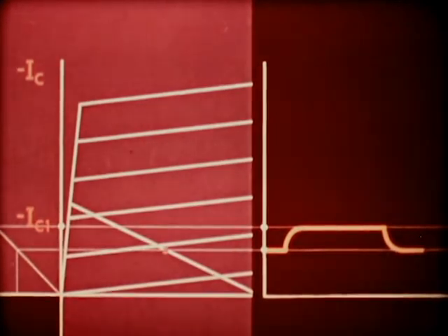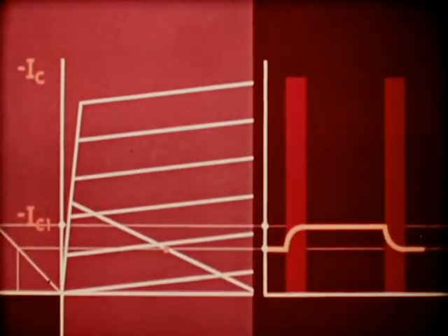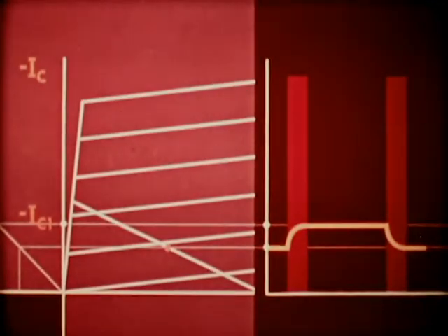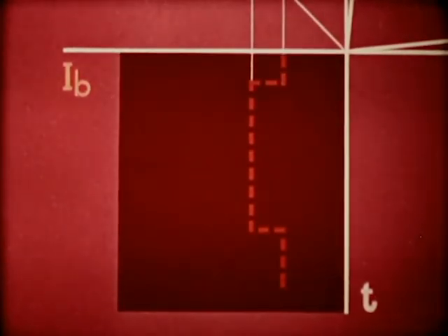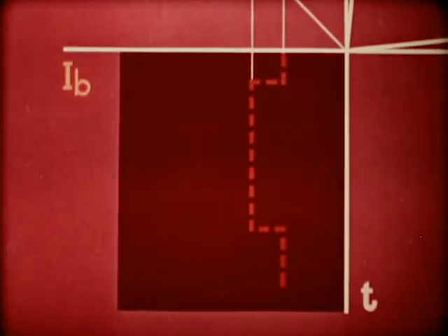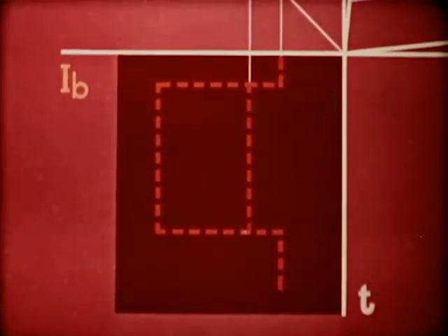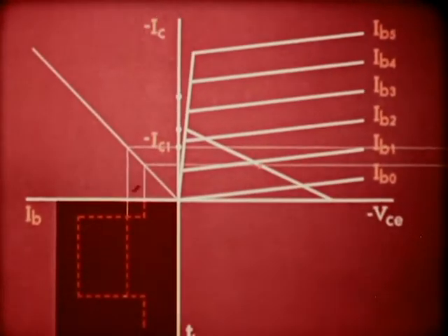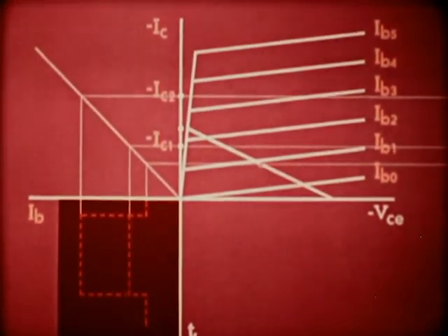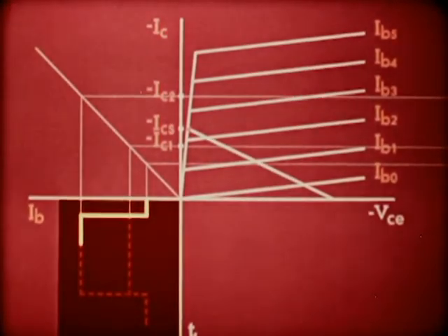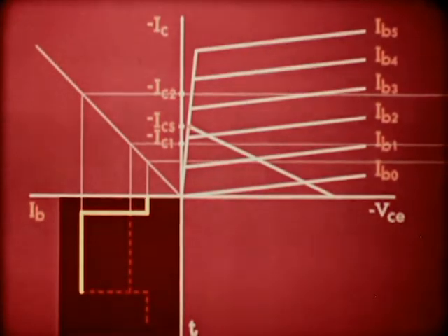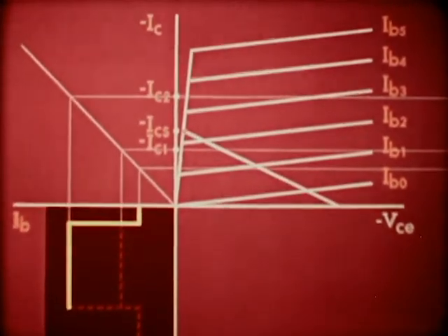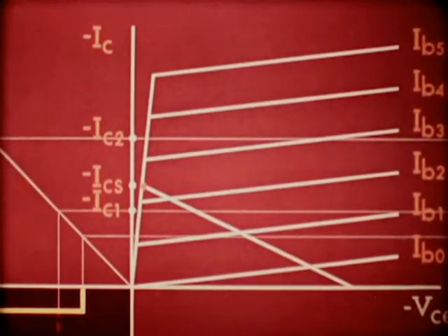In this example, the time taken for these current variations to occur will be rather long compared with the pulse duration. If we now apply a much higher input current, the collector current will be limited by the saturation value, ICS. So TR will now be much shorter.